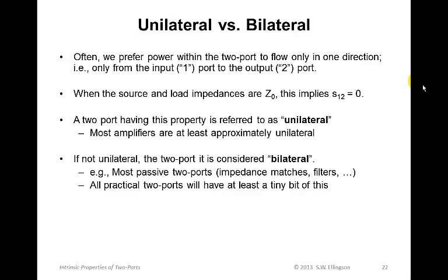If not unilateral, then the two-port is considered bilateral, and that obviously means that S12 is not necessarily equal to 0. For example, most passive two-ports, that is, impedance matches and filter two-ports, will be bilateral. They work in both directions. All practical two-ports, in fact, will have a tiny bit of bilateral property. In other words, S12 will not be exactly 0, but it will be perhaps negligible, or maybe just small enough that its effect is small.